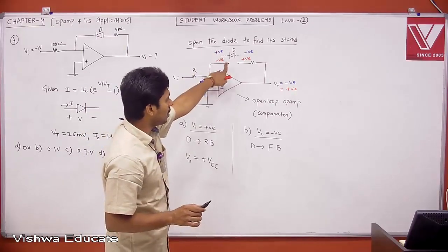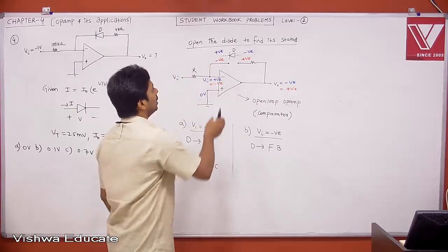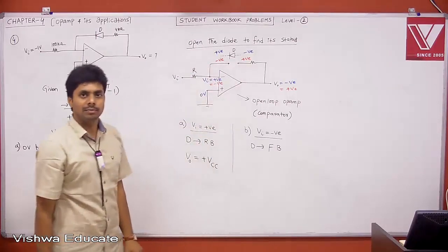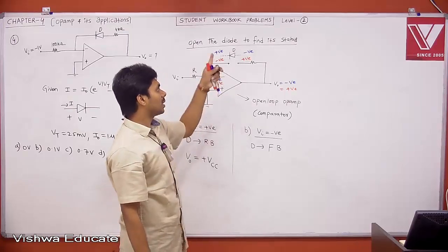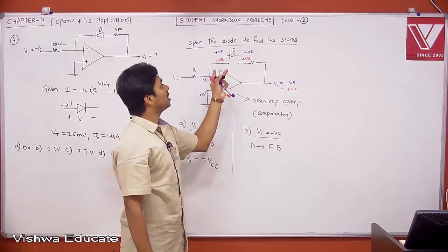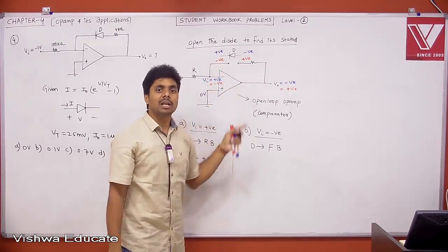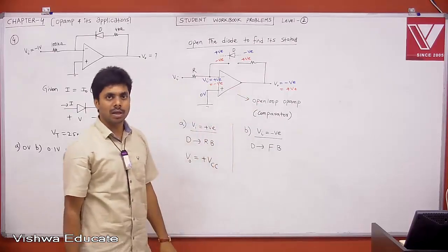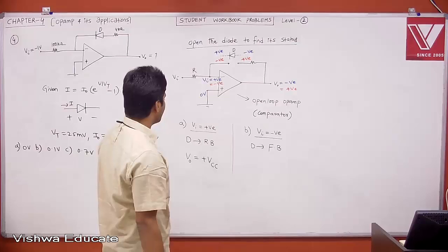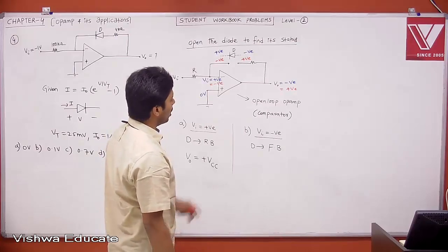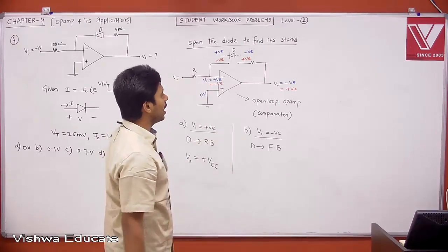When the diode is in forward bias, there is a current flowing through it, depending upon the voltage across the PN junction diode. How much current it needs to satisfy KCL, then to get that much current through the PN junction diode, how much voltage it needs across the diode, that much voltage will be given by your op amp, to satisfy KCL and KVL. That is what we need to write. We will write and then we will solve. Therefore, now tell me what is your V0, if the diode is forward bias.